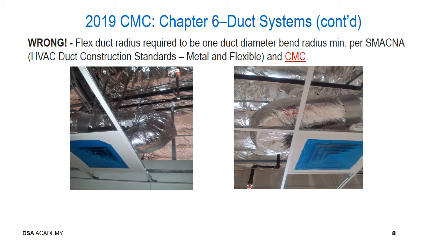And I would also argue that the contractor has not used due diligence in ensuring that the shortest piece of flexible ductwork that is required is being used. There's certainly way too much flexible duct being used in these two applications.